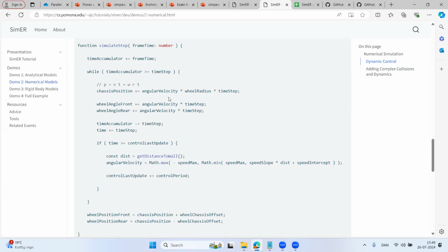But this, like I said, tracks perfectly with what we had before, because it's constant velocity over the surface. It even works in this dynamic case where I'm changing the velocity. This might seem like it's not constant velocity, but it's always constant velocity. I'm just changing it using sort of stair steps. The velocity doesn't change over an integration time step. So that's what I mean by constant velocity. It does assume that my vehicle has infinite acceleration and can go from 1 meter per second to 1.1 meters per second in an instant, but it still works, tracks pretty well.